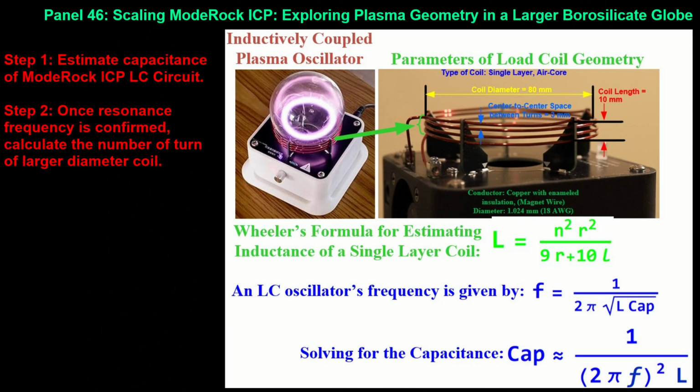Additionally, the 12-gauge wire's insulation should comfortably withstand 3 kV breakdown under normal humidity conditions, which ranged from 24% to 55% at the time of my experiments. Now, the emphasis on precise tuning explicitly ties to the transceiver's role in measuring resonance frequency rather than the coil itself. Detailed calculations for self-inductance, capacitance, turn count, and voltage breakdown are provided at the end of this video.